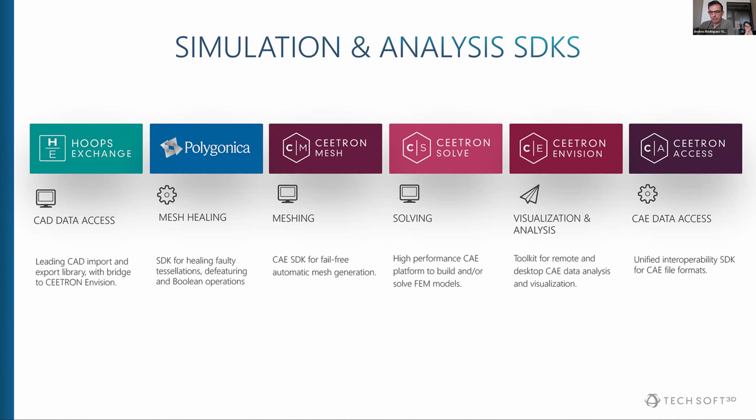If you have the mold and you want to add some runners, then Boolean operations on meshes are quite cool. CEETRON Mesh does the meshing, 2D, 3D meshing. There's quite a few meshes. The most popular ones are those surface mesh for triangles and quads, and volume mesh for tets, and possibly some pyramids if there's quads on the surface.